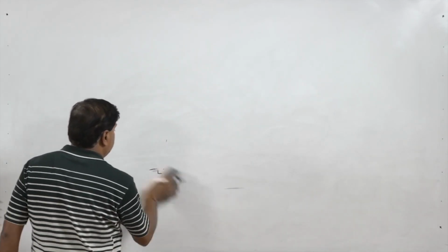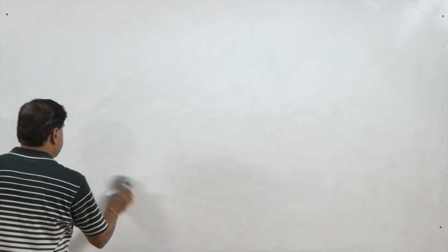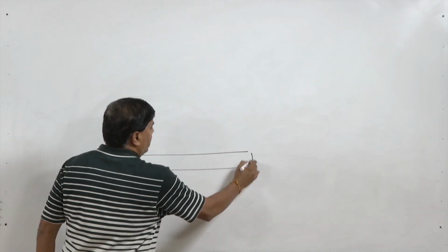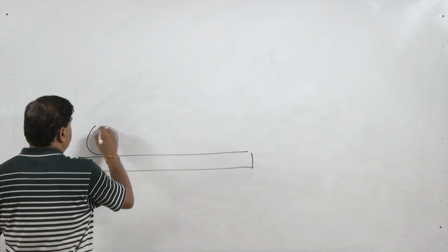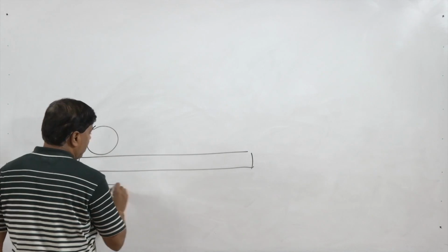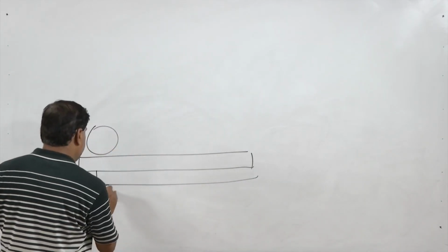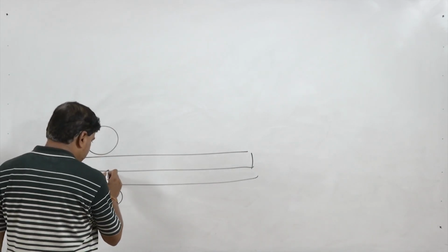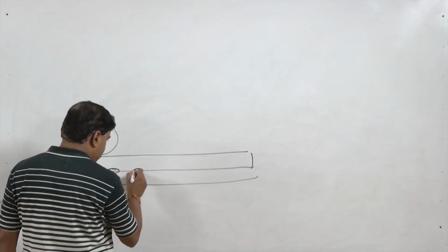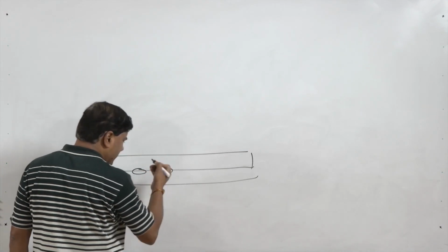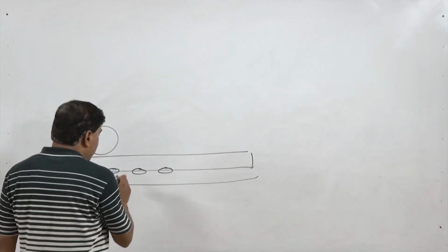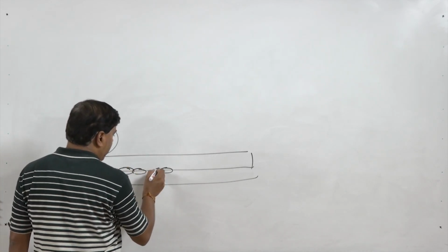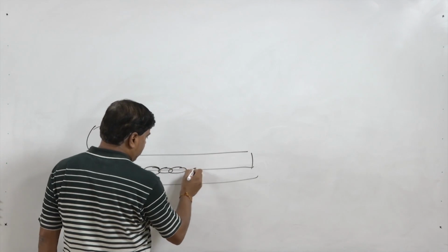Similarly, in case of the seam weld, seam welds are made in three ways. Seam weld means continuous welds made with the help of rollers, which roll continuously while current is fed. Here the seam can be made like this: one spot, another spot, another spot, like tack welds, or in an overlapping kind of tacks.